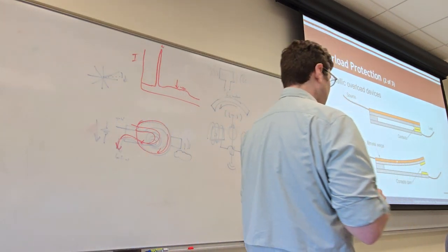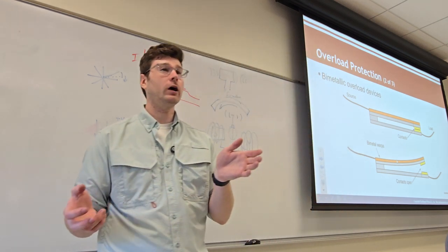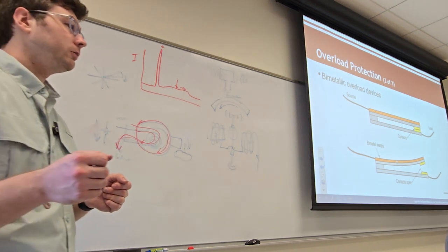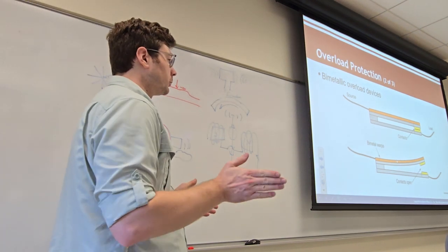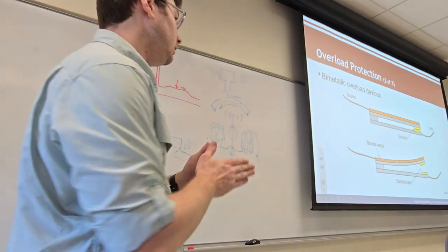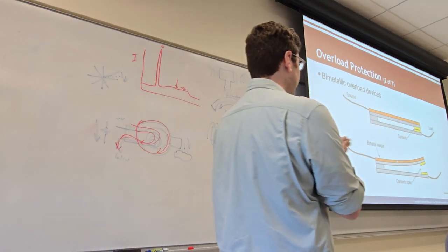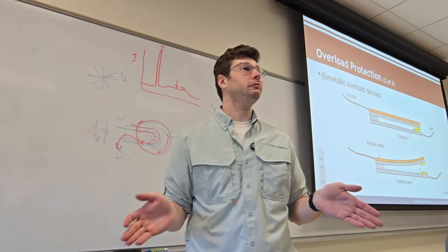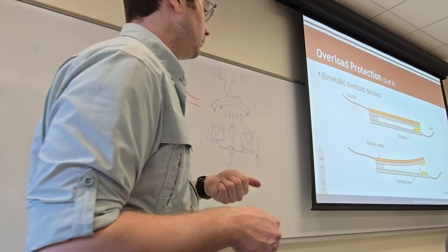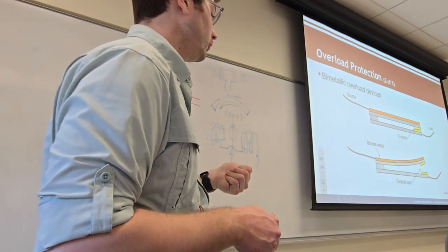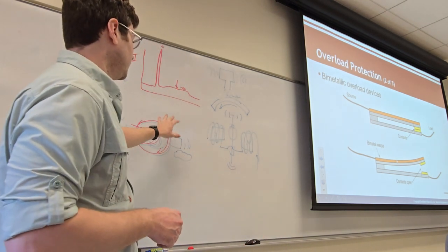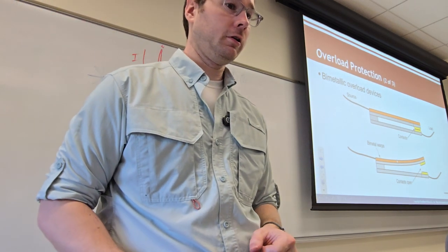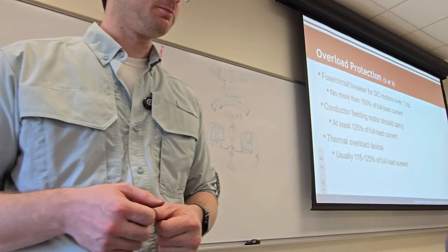Okay, it's again that piece of metal that I was talking about before that was so common in thermostats that changes its shape according to temperature, and when it goes over some temperature, it'll warp. And once it warps sufficiently that it removes two contacts from each other, it's like opening a switch, and it removes the flow of electricity. Okay, this is a motor that can save itself, essentially. When the temperature eventually goes back to normal, you figure out that it stopped and you remove the stuck condition, it'll continue to work and not have its windings melted, right?